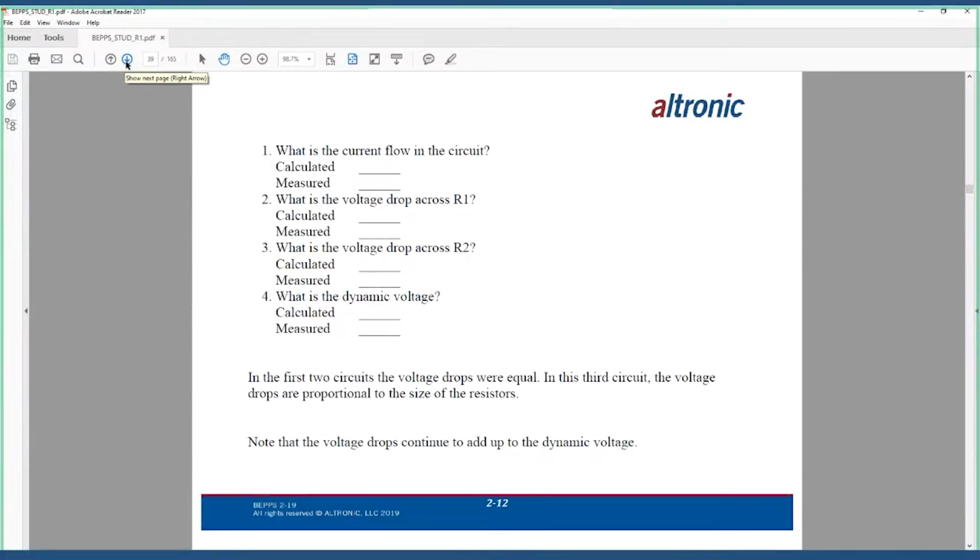Hey, John, this is Greg. Let me pull up my calculator here. So remember, E over I equals R. The question is, what is the voltage drop across resistance 1? 0.8182. Okay, yeah. So you didn't round off the way I did, but yeah, 0.81, right? So that's the voltage we should see.